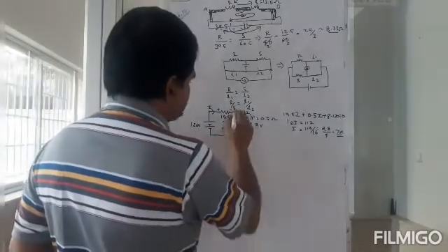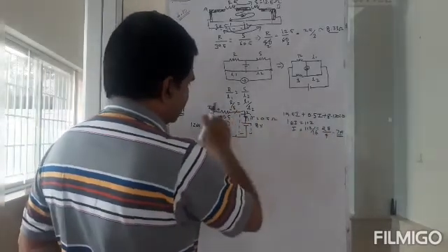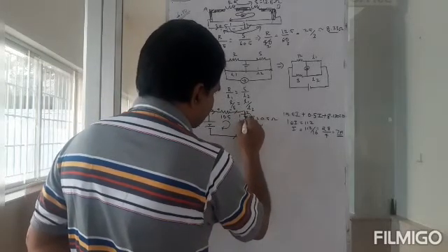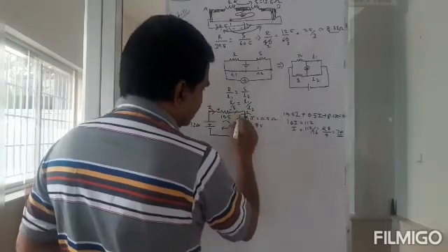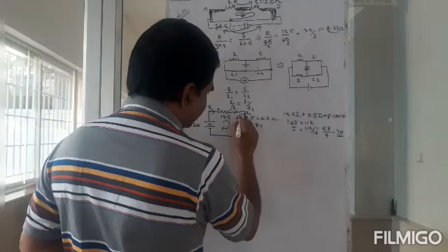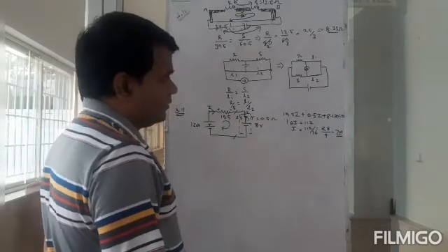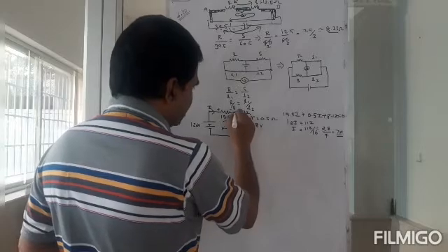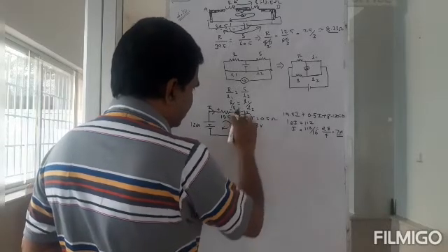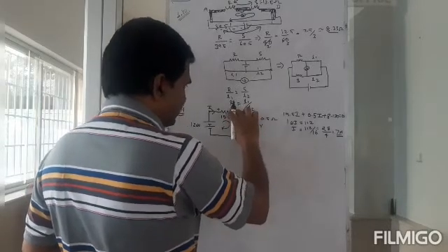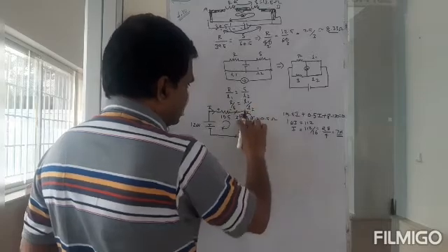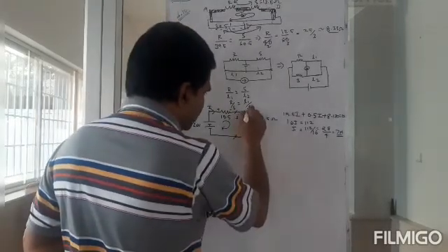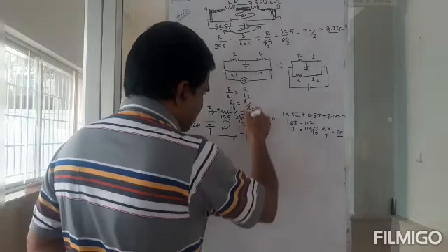Okay, now what is the terminal voltage? Well, 7 amp is the current that is going to go through this. Then what is the voltage drop across this? 7 into 0.5, it's going to be 3.5. Right? So that's 3.5 volt. So I'm talking about the potential drop between the terminals of the battery. These are the terminals, right? So what would be the potential across the battery? That would be the potential difference between this and this.